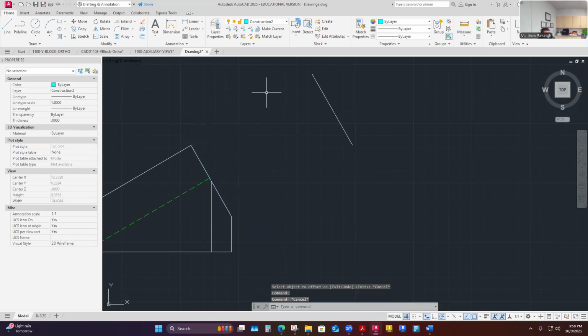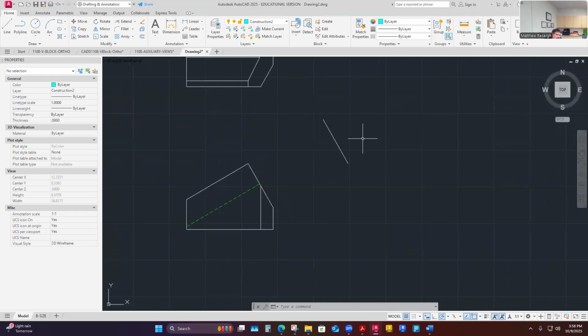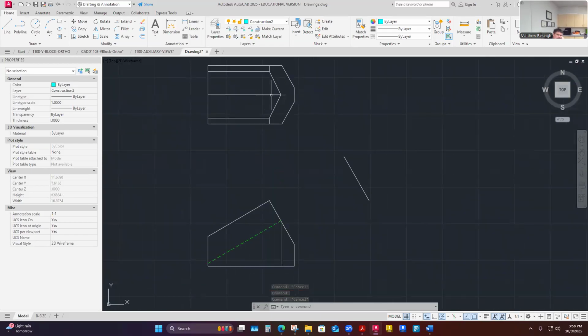So if I hook up my projection from that to that, it should be in perfect alignment with this line here. And then what I did is I thought of this as more of my center line, right here. And I thought, well, this is 2 inches deep here. So I thought I would offset this particular line another inch on each side, and that would be the boundary area for this particular auxiliary view plane.